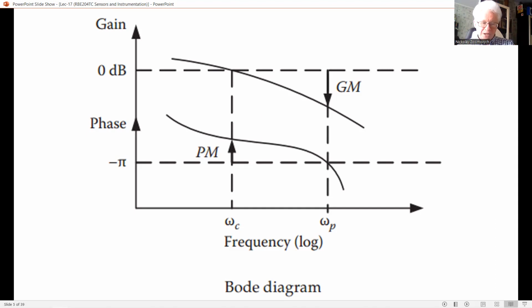It follows that when the overall phase lag of the loop transfer function G times H is equal to pi, the loop phase lag becomes 2 pi, which means that if a signal of frequency omega travels through the system loop, it will not experience a net phase lag.